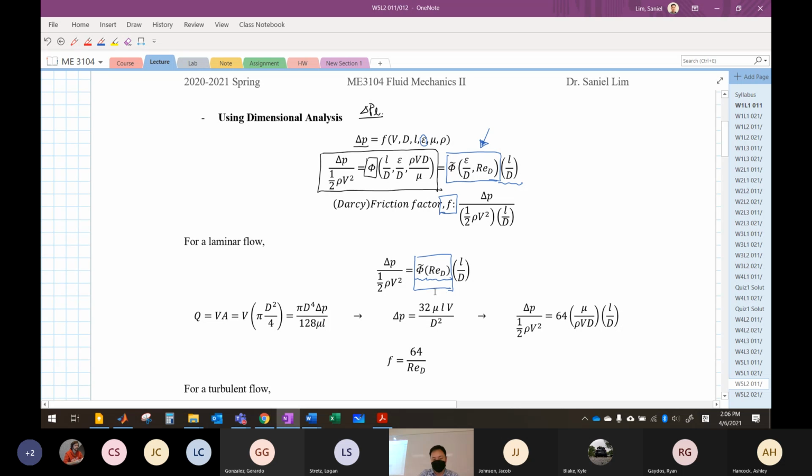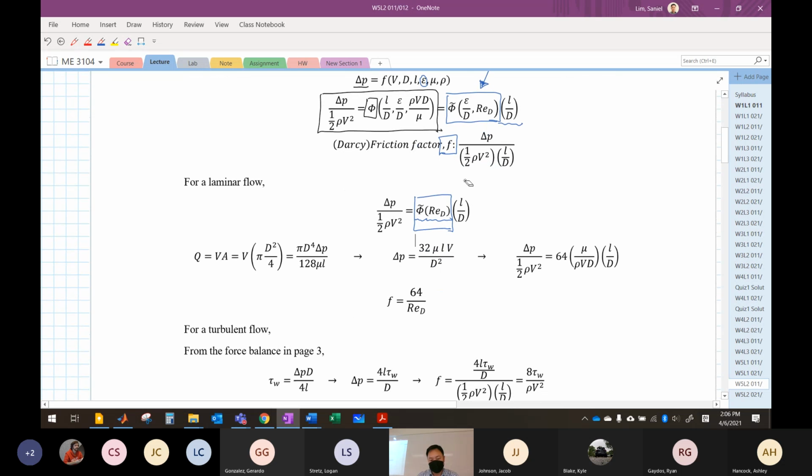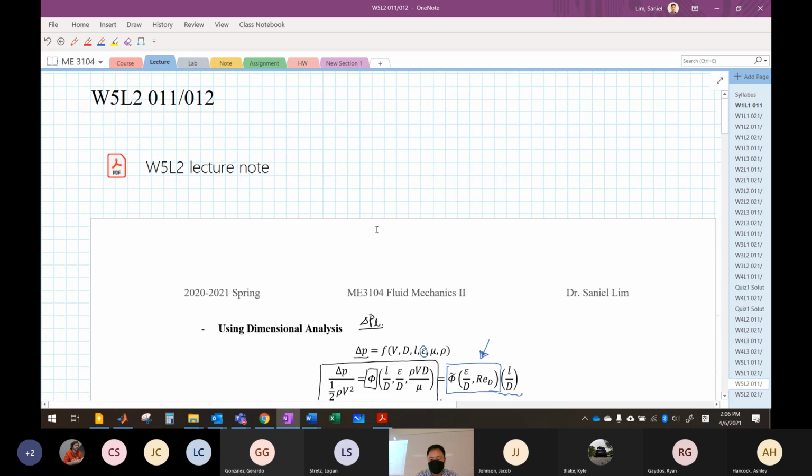All right. I know this relationship should be valid, this whole thing. Then we have an exact solution from the Navier-Stokes equation, or from the first step, using F equals ma. Either way, we can have the exact solution for the flow rate, the velocity profile, the average velocity, the maximum velocity, and so on. So I just brought the exact solution of the flow rate, Q. It's pi d to the fourth power, pressure drop, over 128, viscosity, L. That's all given here in the previous lecture.